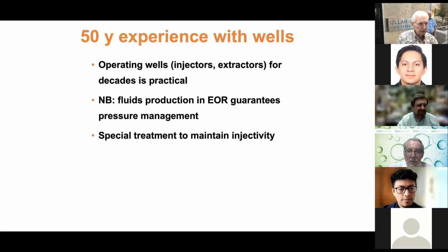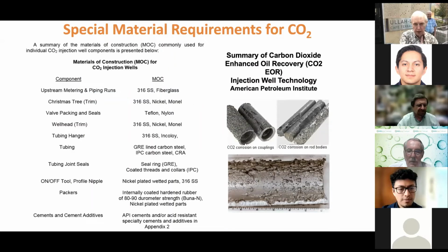And I don't know much about this, but I'll basically show a slide that somebody gave me to see what sort of treatment requirements on the method of construction on the right-hand side for each wells to prevent the different things. The history is, and I took this out of the presentation, is that injectivity of a well typically declines with time. It declines during CO2 injection. It declines during water injection, and so things usually lose injectivity, and the wells do have to be treated periodically if you can't live with the injectivity.